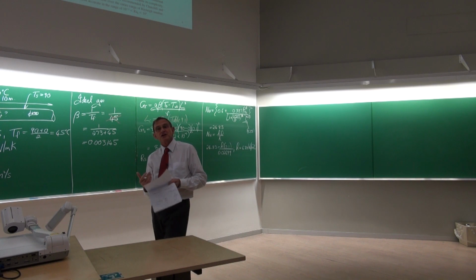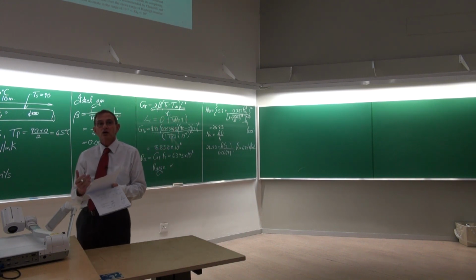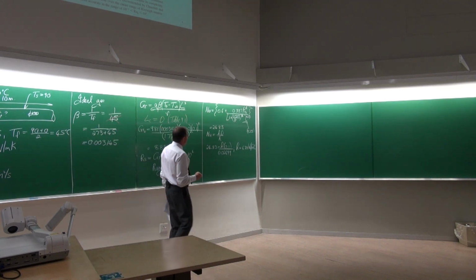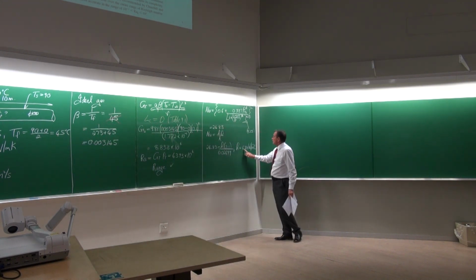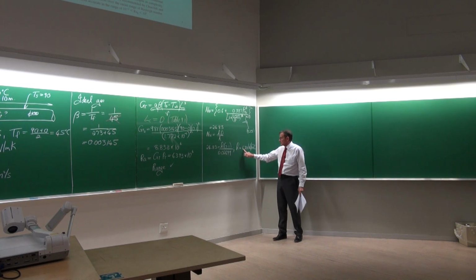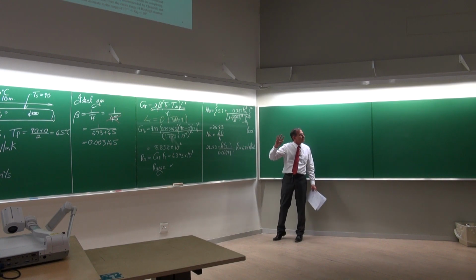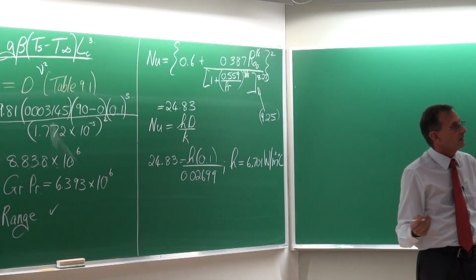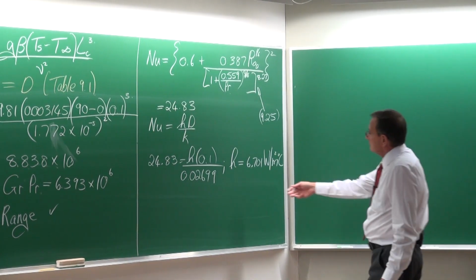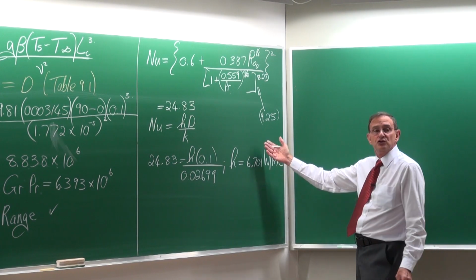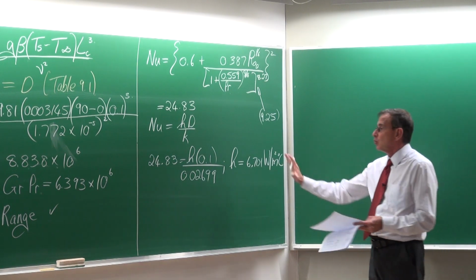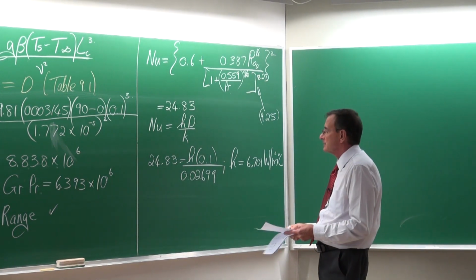And when you've got two-phase flow, like condensation or boiling, order of magnitude is 10,000. So if you remember that and you calculated, for example, this heat transfer coefficient as 6,701, then the red lights should go on. Anything from 1 to 10, 20, 30, 40, those are the typical order of magnitude of heat transfer coefficients.